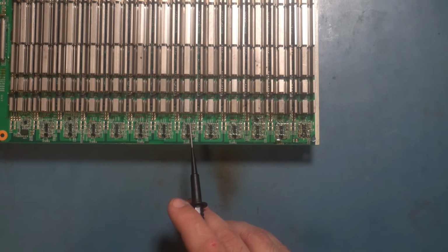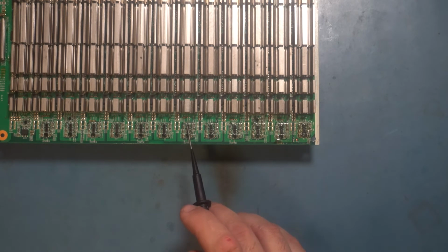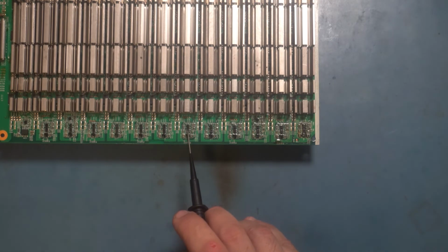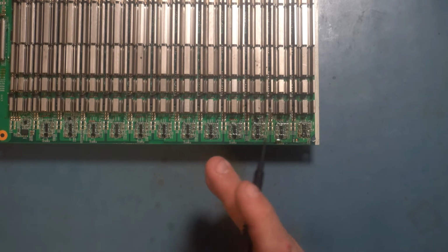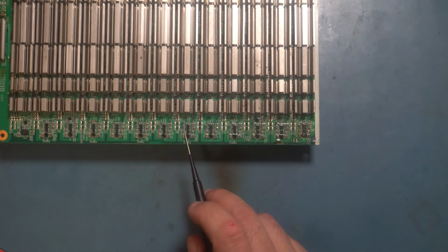And rule of thumb, usually to regulate, you need at least half a volt higher, right, for some overhead and for some of the chip that's going to do the actual regulating. So if I were to do 1.8 volt, then I would need at least probably 2.3 volts. And this is like bare minimum. So you probably like double that, really. Like doing 1.8 volt from 5 volts is really easy.